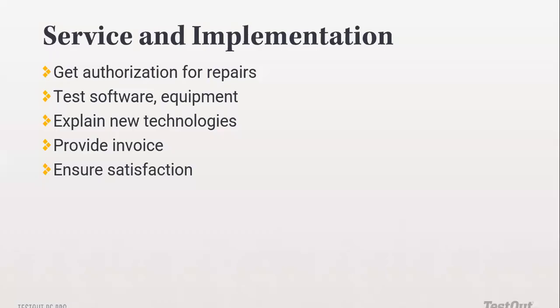I was just saying that if someone comes to you and wants you to work on their device for whatsoever reason it may be, and they tell you this is how it is behaving, this is the problem it has, before even checking it, make sure in front of that person, you test that device and make sure that every single component works. Because what if you don't test it and tomorrow something else was bad in there?